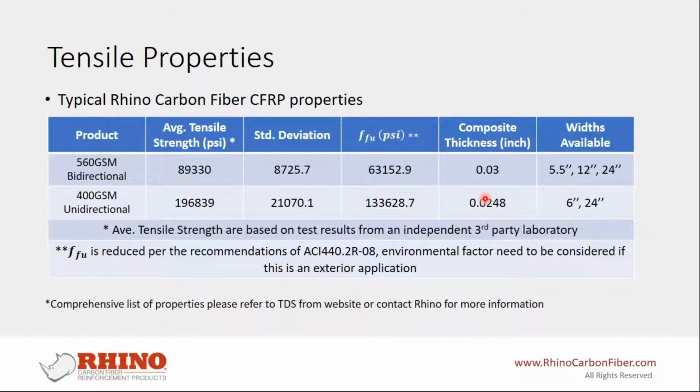Then you have the composite thickness. Those numbers are from the lab as well, but during practice, it should be noticed that the thickness will vary. But as long as the CFRP is saturated, you should be fine. And the CFRP, of course, comes with different weights based on your need. Those weights should be able to cover a broad variety of applications.